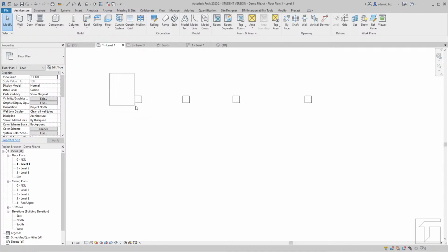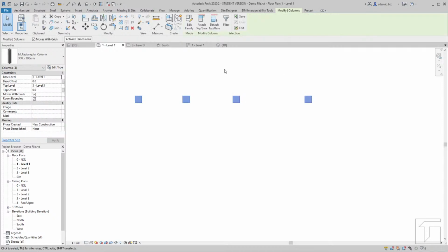Now notice as I hover and encapsulate all these columns, it turns to blue, telling us that we have successfully selected these columns. To finally select them, I'll just release my mouse, telling us that these 4 columns have been selected. So let us now copy them. To execute a copy command, it's here on the ribbon menu. Under the Modify tab, we have this copy command here.